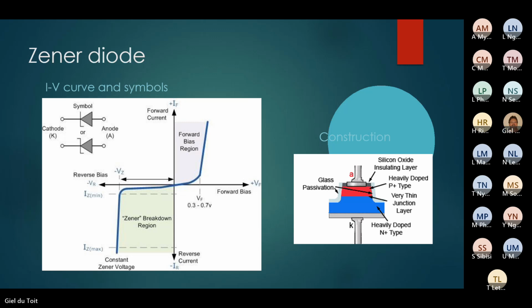All right. Now, in this case, the diode will be reverse biased and there will be a reverse current flowing. That current will be on this axis, so it's minus, say, 100 microamp. And the reverse voltage over it will be, say, minus 10 volt in this case. So about minus 10 will be about here. That means it's reverse biased in this region. When you look at the questions in the tutorial, this is one of the questions.